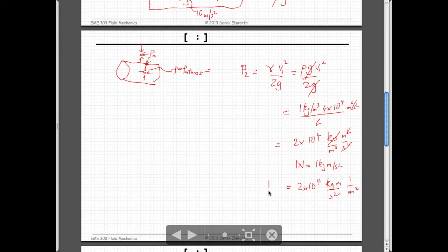So the pressure that's applied is this. If you multiply the pressure by the area, to a rough magnitude, you get the size of the force that you're applying to the truck. So pressure times area equals force. And if you know what the force is, and you know the mass of the truck, you could figure out what the acceleration is. So, a relatively straightforward calculation, but one that comes out of just applying Bernoulli.